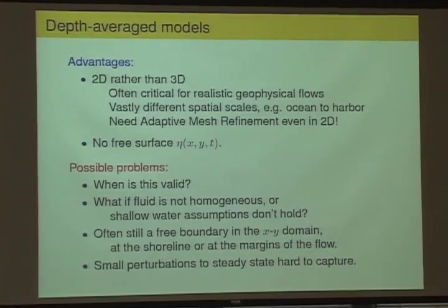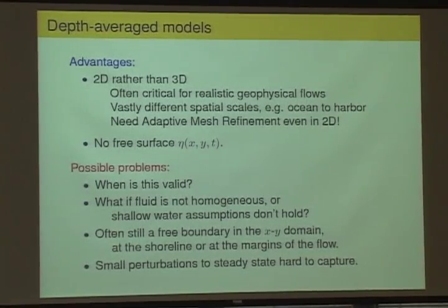There are other problems, as we saw in this video, as this flow moves out at the margins, the edges, you've also got a boundary. But as you might have noticed, we're always solving on rectangular grids, or logically rectangular grids, maybe latitude-longitude grids on the sphere, but they're just rectangular grid patches. So we don't try to use a grid that conforms to the boundary of where the fluid is and change those grids.